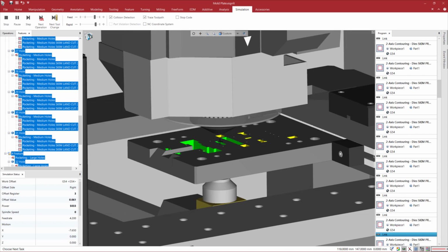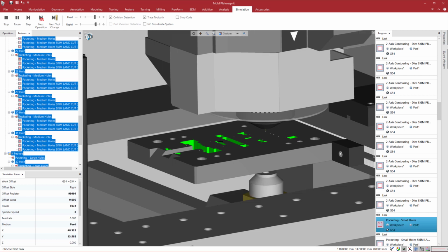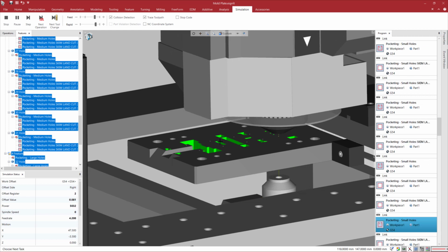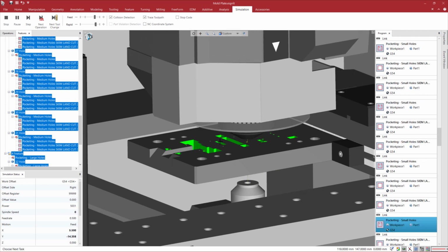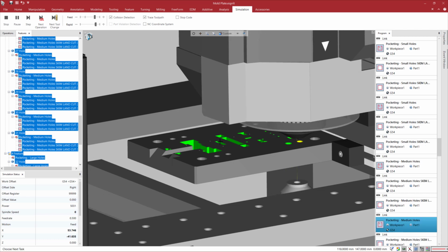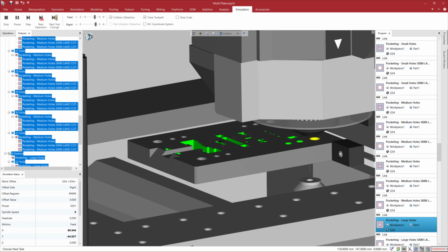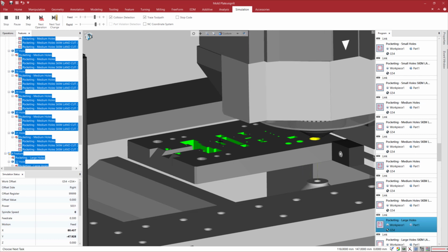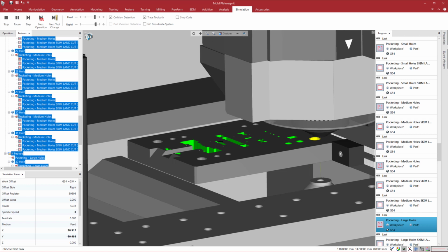And once he's removed those slugs from the cutoffs, then we can just let this run overnight, throughout the day, whatever we need, unattended machining, to make sure that this die block gets cut correctly without having someone need to sit and babysit the machine. So it's a really helpful way to be able to program. So now that that's done, we'll move on to our next heat sink part.